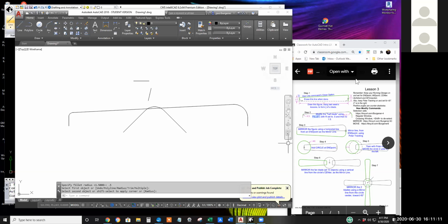I wanted to know how, instead of making a corner there, you have two lines, they're not touching. How do you make them come to 90, or just to a point and touch one another? That would be the exact same process, but set the radius to 0. Oh, so easy. Thank you. Right click, radius, 0, enter, click, click.